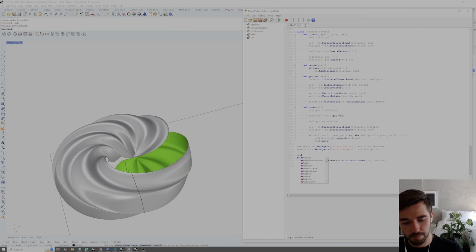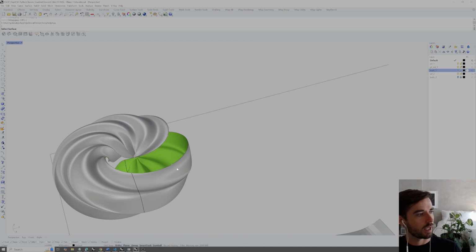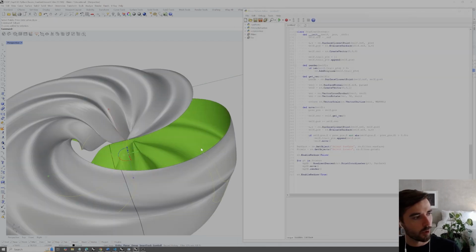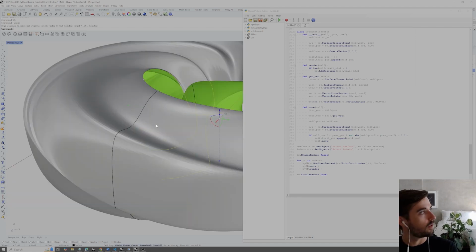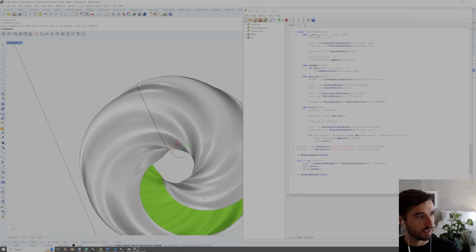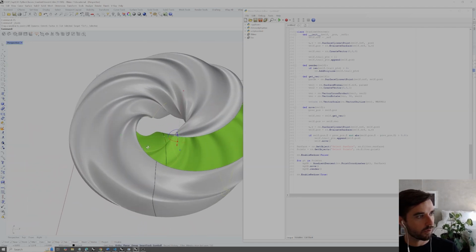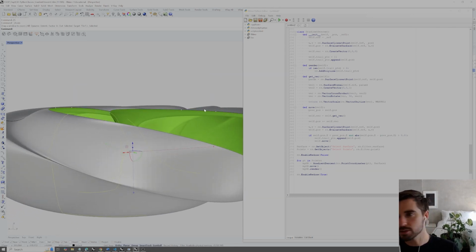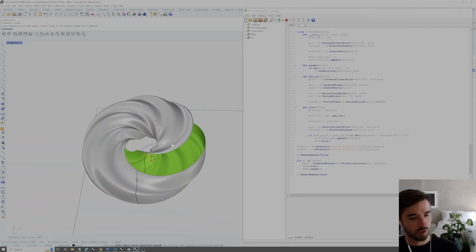To speed this up, we can just turn off our redraw. So set redraw equal to false. And then after we run through the entire loop, set it equal to true. Now hit play, select our surface and then our points. So now it just thinks for a moment, draws out all of our curves and simultaneously displays them. So we see 4 of these curves being drawn out. These other ones must be at local minima, so they're not making any curves for us to draw out.